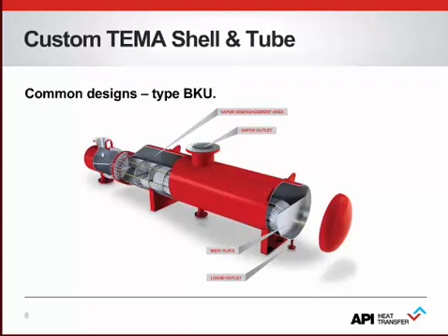requirements. A boiling liquid will produce vapor that disengages from the liquid in this enlarged shell space and exit the top vapor outlet. Any remaining liquid will exit through the liquid outlet after flowing over the internally mounted weir plate that's shown, which acts as a dam to maintain internal liquid levels.